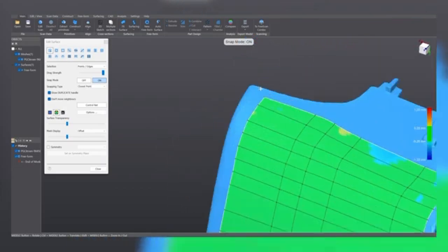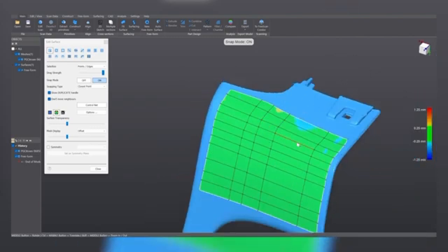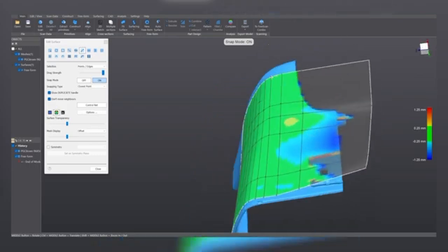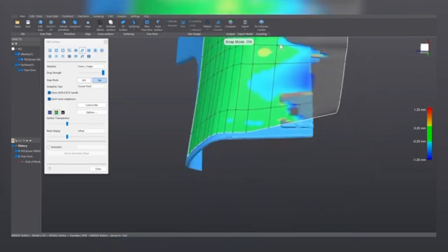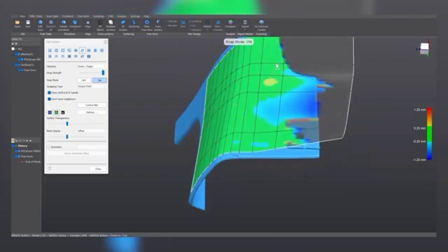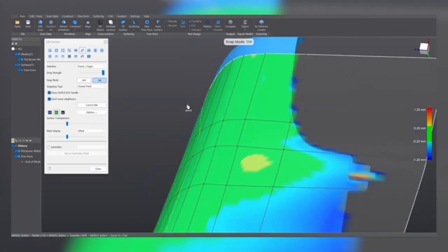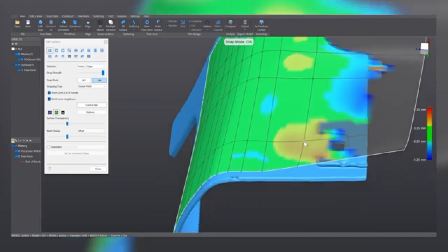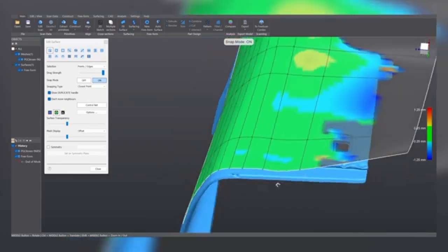And now, instead of extruding more and more faces, we are going to extrapolate the current surface that we have. So we click on here and we select the edge and we extrapolate it. Okay, now we have points, vertices of this surface that are onto the mesh and points that are not onto the mesh, right? So let's first take care of the points that are onto the mesh. We go to the manipulate, and with the snap mode on, we move them a little bit and let them snap onto the mesh to give us a surface that adjusts well to the mesh.